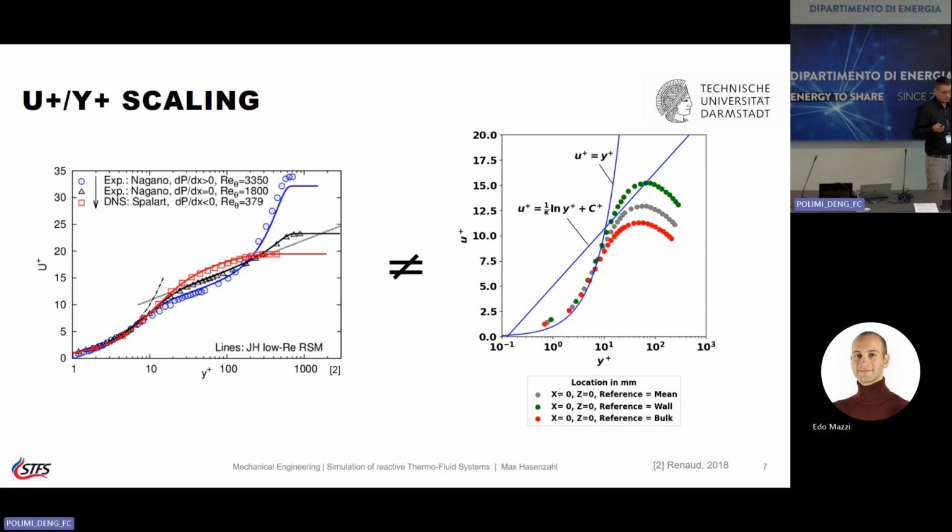So if then, of course, you think, okay, I make some assumptions about the temperature, or I select the mean temperature to do the scaling, I think you have to be very careful making interpretations whether you have a favorable or adverse pressure gradient just solely based on comparing this to incompressible DNS. So this is something you really need to be a little bit careful on.